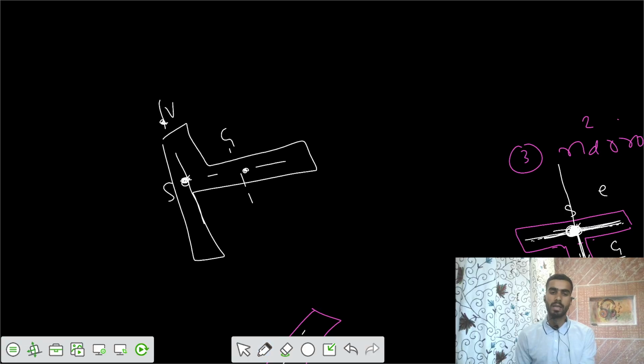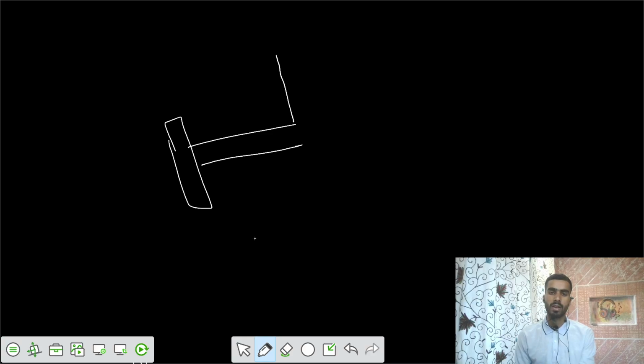And after that you can take an I section. Let's say this is your I section, but the two different flanges are not equal. Let's say this has some moment of inertia I1 and this has I2. So the centroid would be somewhere here. Let's say the centroid is G, somewhere here. And I would ask, what is the location of that shear center?